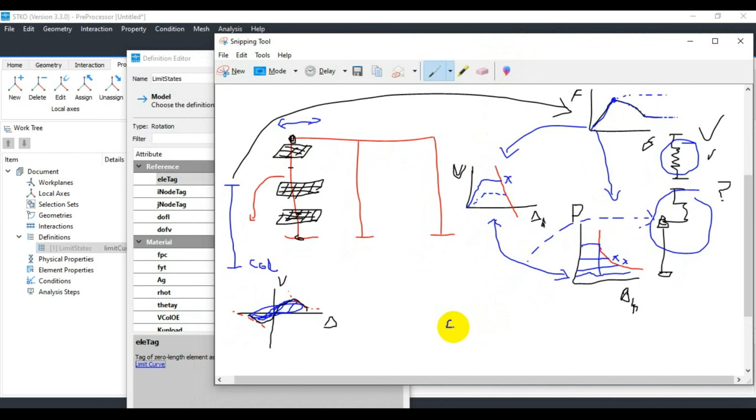So, for example, if we have a truss element, we only need one uniaxial material, or if we have a spring element that we want to define, we need only one material to define it in terms of force-displacement, stress-strain, moment-curvature, or moment-rotation response. So in OpenSees we can take those elements and get the response from them, and you can imagine them like this.